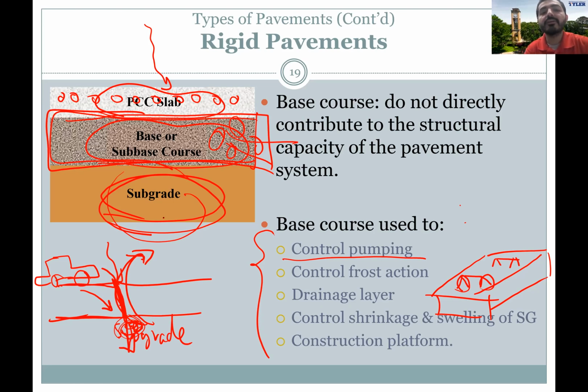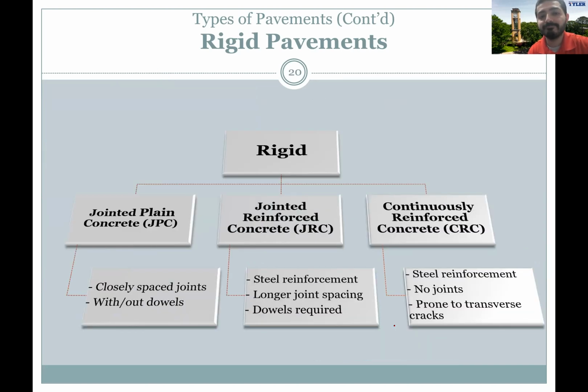and therefore the reinforcement is not going to be exactly at the center. But if I have a good base layer, I can tie these bases into the base or the subbase course layer, and now I'm going to make sure that by the time I'm pumping the concrete, those reinforcements are not going to move at all. So that's why it's a good construction platform.